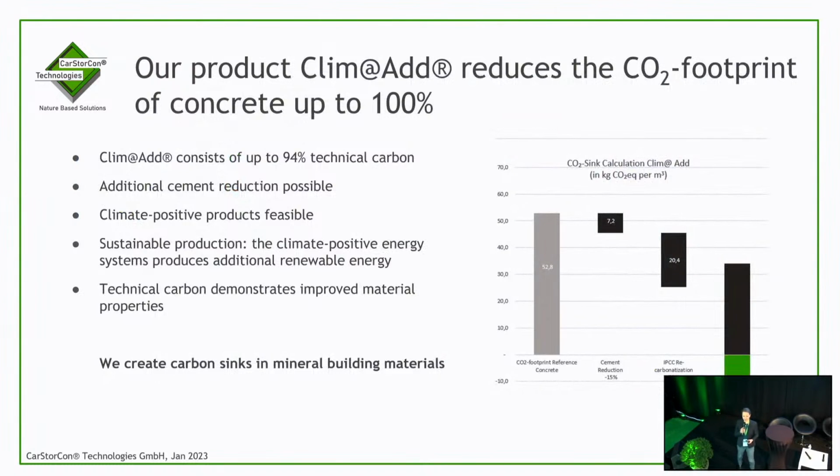And for us, it was very important not only to have this carbon sequestration potential, and I want to explain this here on the graphic. One of the main points is really improving the functionality of the concrete. Otherwise, an economically viable case is going to be difficult to reach just by the storing potential. So what we see here, of course, is a carbon footprint reference. Then, on the next, the little one there, we actually managed to tune the biochar in a way that you can reduce the cement that you are using for the concrete quite significantly, and even though reducing it, reach the same compressive strength and flexural strength, and even improve it depending a bit on the type of concrete.